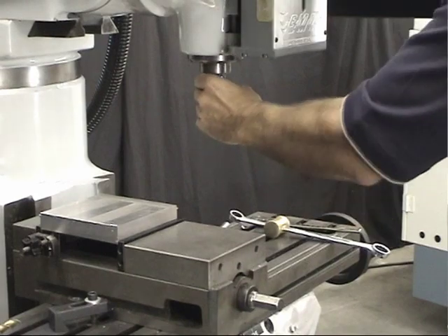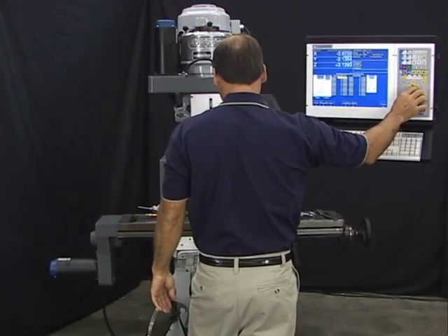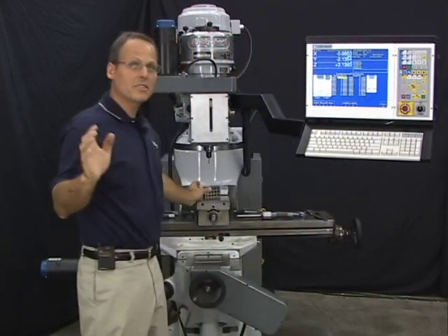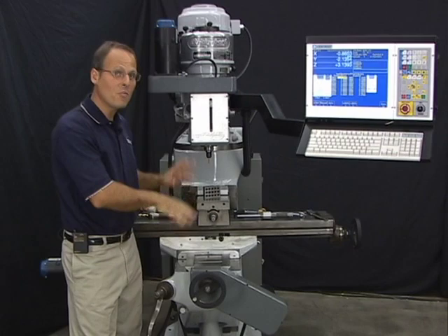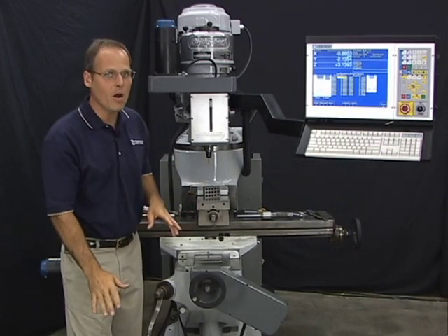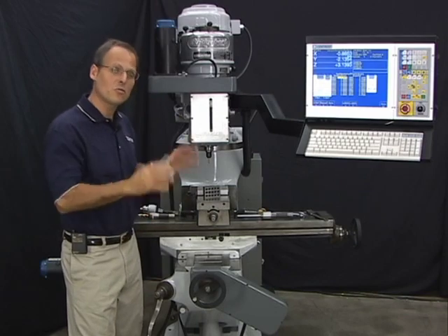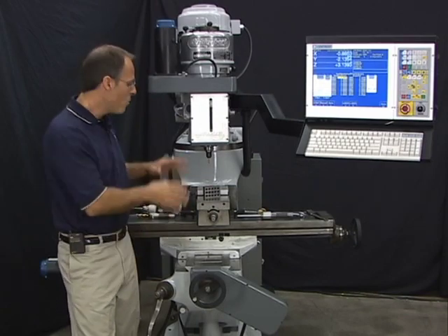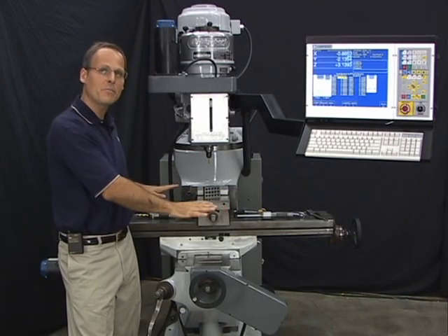Okay, I got my tool number 1 loaded up. Jog it back over the top of the vise. Now, just as a reminder, during this whole process, you don't want to move the knee. When we're done, we can move the knee wherever we want. So if we had to get a big part in there, the machine with these same 3 tools, we could do that. No sweat. But while I'm measuring the tools, the knee's got to stay at the same position.